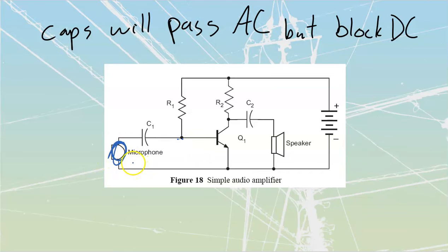How does an inductor act in DC? Well, it gives me 5 tau of opposition. After that, it steps out of the circuit. So in essence, if I did not have that cap inside of there, that microphone would act as if it were a short down to my negative over here. And if that were shorted out at the negative, we wouldn't be able to get 0.7 volts, which would mean that my transistor would be shut off. That'd be if I was missing that one. If I was missing this one, same deal.